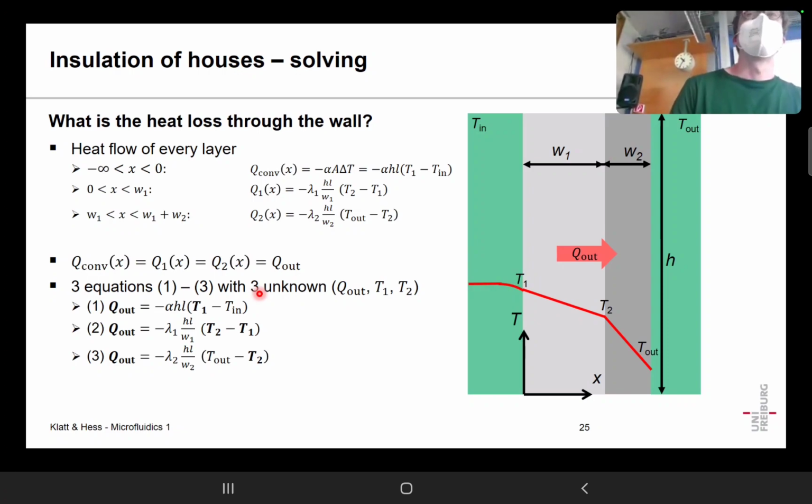Go for it. I don't want to destroy it more, but isn't that the problem, since the gradient of the temperature would have step behavior once you change the material from that point to W2, and the heat flux would change stepwise?